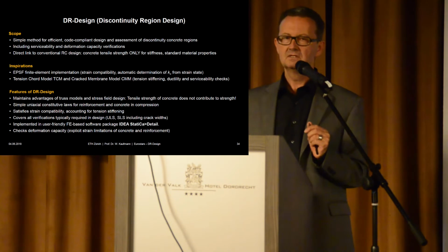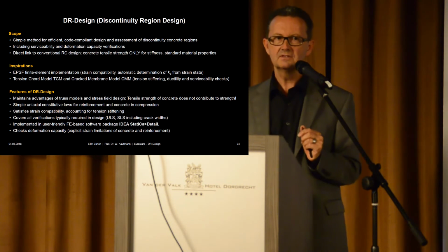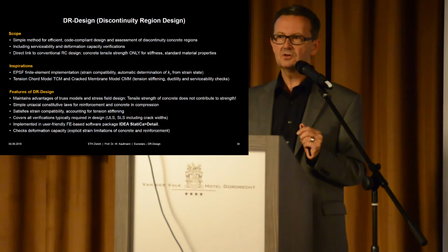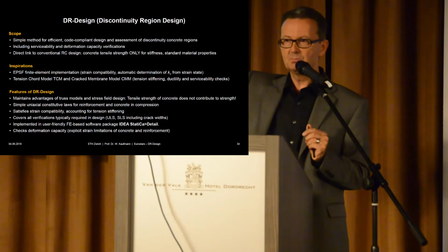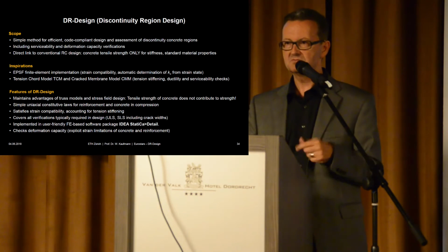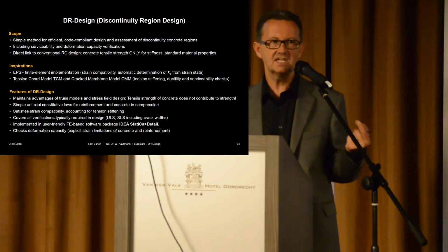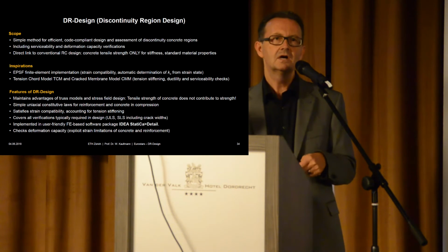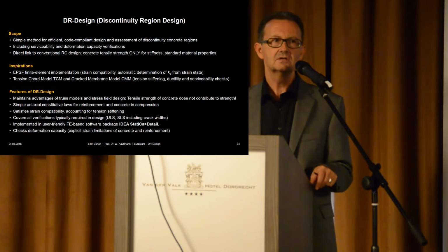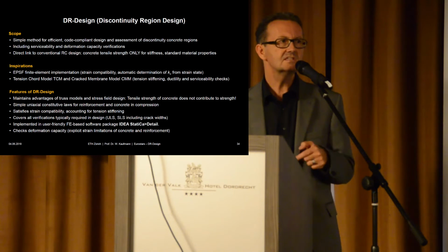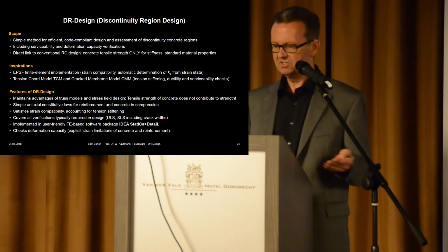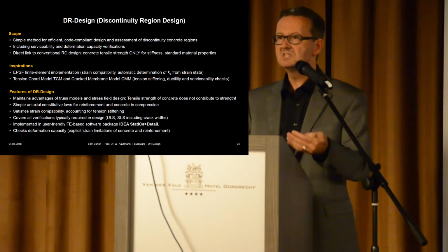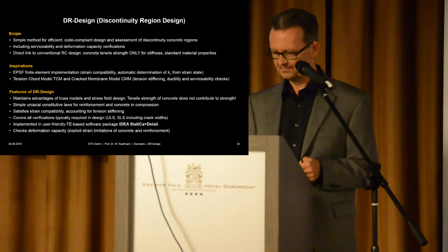So that's compressive strength of the concrete and the grade of the reinforcement with the ductility class, which then gives us the ductility properties that the program uses. It can be changed manually, but by standard it's B500B with 0.05 of elongation of the naked steel and 8% strain hardening. That's what's in there. And that we know in design because we ordered these materials with these specifications.